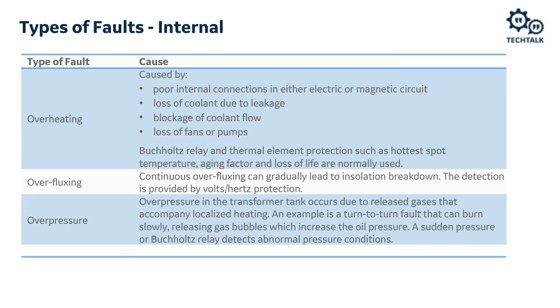Now, we haven't noted it on the slides here, but another major point is internal electrical faults such as winding phase-to-phase or phase-to-ground faults or an open winding, where we would employ our transformer current differential protection, which is what we will be talking about in detail later. Along with the Buchholz relay, our current differential element would also detect winding interturn faults, insulation failure faults, and tank faults. For most internal faults, a current differential element is used.